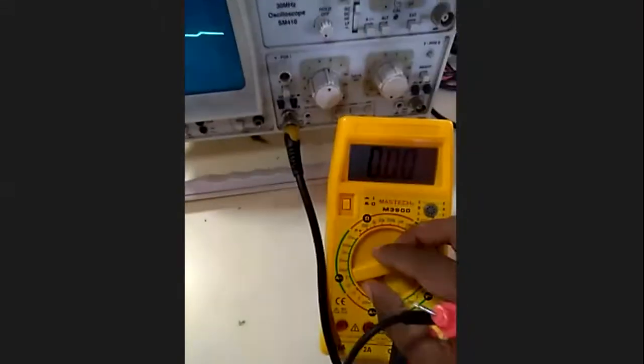This is the actual output at the capacitor. You have almost a straight line, but there is a small variation. That small increase and decrease is what we call the AC component, which we call the ripples, which we are going to find out. So going on to the circuit, let me put this in AC voltage.